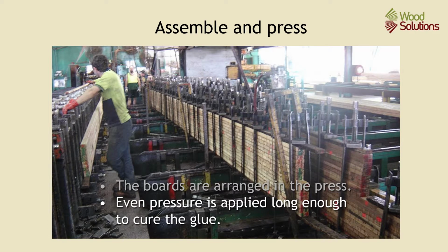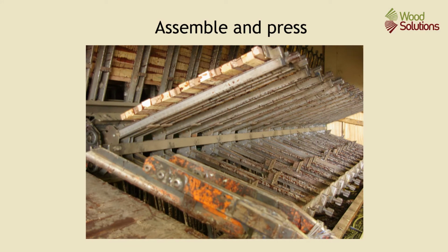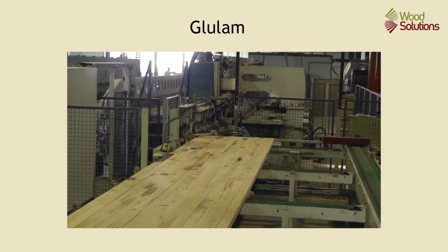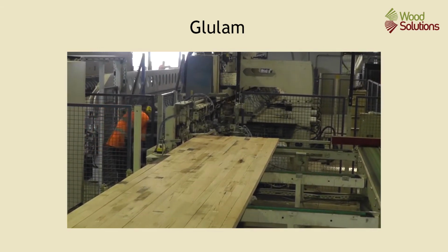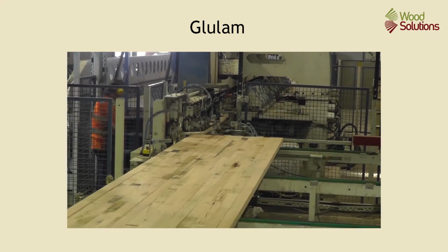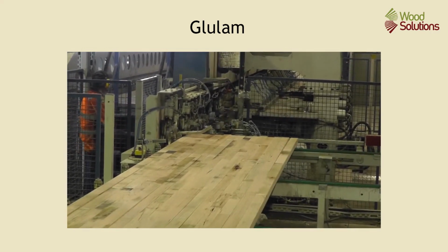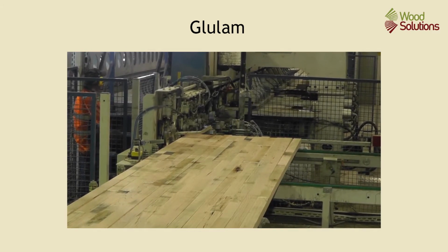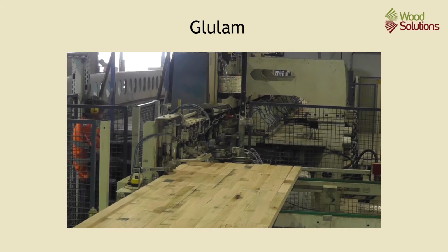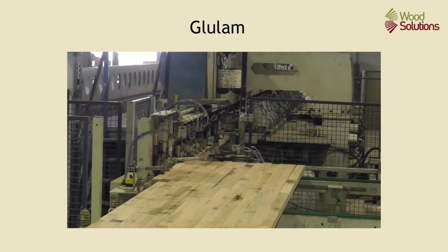These presses use screws to press the timber elements together. Others use hydraulic or pneumatic systems. This is another screw-type press for making thin beam products and bench tops. This is a largely automated gluing operation. Boards are fed onto the platform, held, and then glue is applied as the boards are drawn forward and go into the press. This is a continuous feed press.